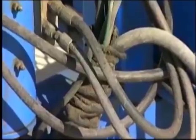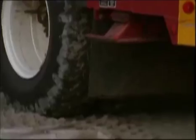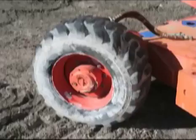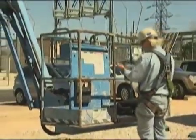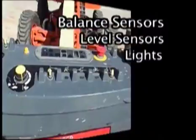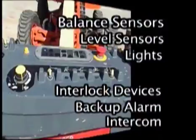Check the hydraulic system for possible leaks and the fluid level for proper amount of fluid. Outriggers should work properly and should always be set. Emergency stop buttons should work correctly. Tires must be properly inflated and inspected for damage. All safety guards should be checked for malfunctions. Check balance sensors, level sensors controls, lights, interlock devices, backup alarm, and intercom for proper operation.